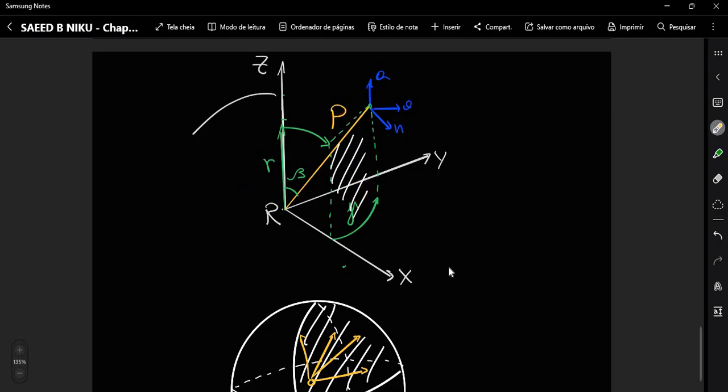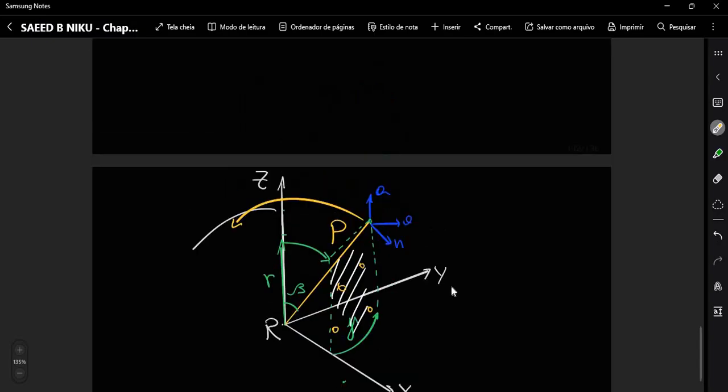So as this is a sphere, now we can put the end effector right here, right here, right here, right here, and we can do a transformation so that this end effector goes to this point, and it can translate up here. So a spherical one and an articulated one give us more, they are not limiting us in the 3D space.